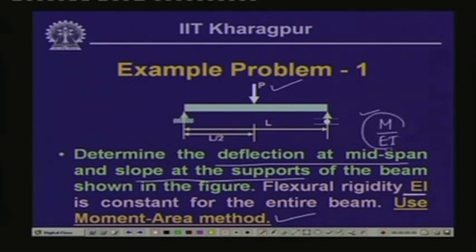Now, to obtain the bending moment diagram for this beam, as a first step we need to evaluate the reactive forces. So, let us call this end as A and this end as B. The reactive forces acting at the hinge are RA and HA, and at support B is RB, as you have seen earlier, and since there is no horizontal force, HA will be equal to 0.